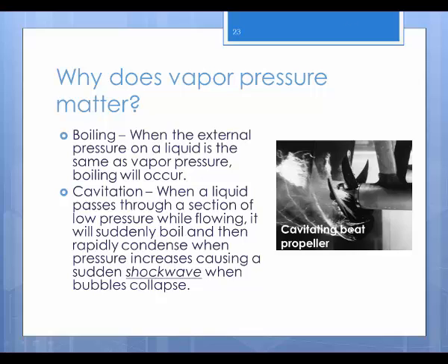That's bad, because you'll bring fluid through a zone of low pressure, and it'll vaporize into bubbles. And then as soon as those bubbles go into a higher pressure, higher than the pressure inside the bubble, the bubble rapidly collapses and creates a shock wave. And that shock wave does a lot of damage to equipment like propellers and pumps and pipes and elbows and things like that, in a lot of flow systems.